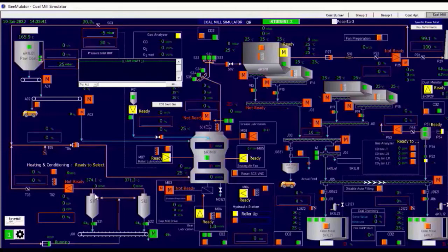Then the hot gas from the preheater is drawn using a booster fan, and fed into the grinding mill system. This hot gas is used for drying and grinding of materials in the mill. Before starting the mill operation, this hot gas is used for heating up first, until the mill outlet temperature reaches conditions according to the specified operating standard.